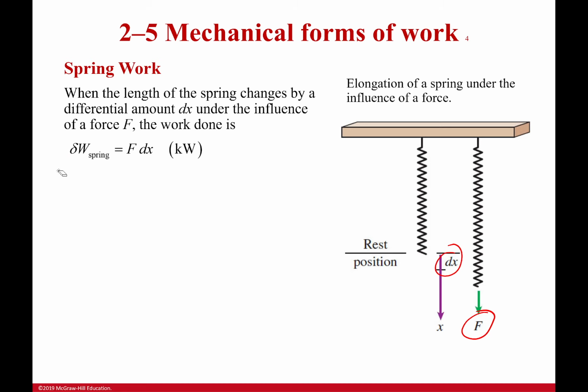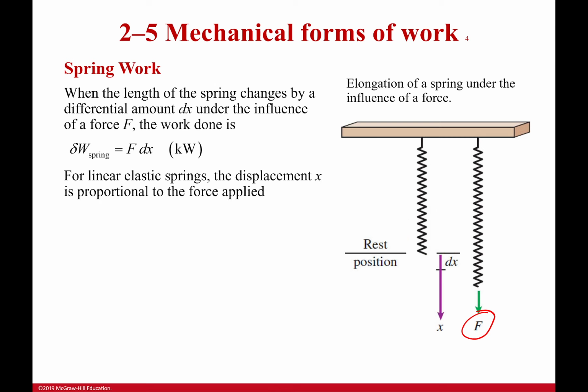The reason is that every infinitely small amount that I stretch that spring increases the force it takes to do so. So if I'm stretching a spring from here to here, to begin with, it might take a force of, let's just say, 5. Then it'll take a force equal to 6 to go a bit further, and then force equals 7. You can see that the force actually changes with distance. So this is a bit more complex than you might think, and I will have to integrate that force to figure out the work.